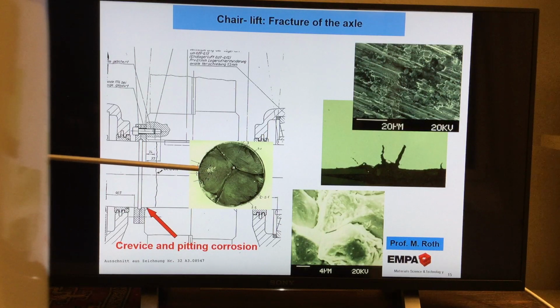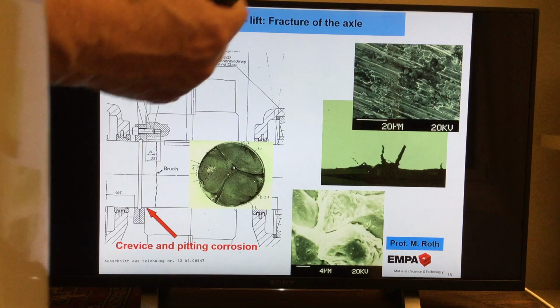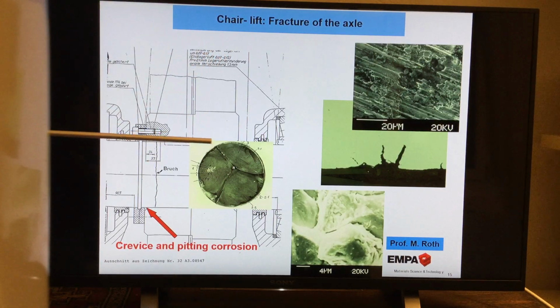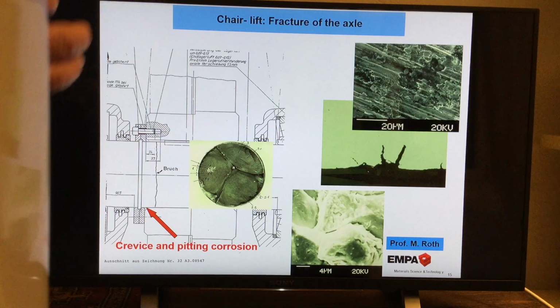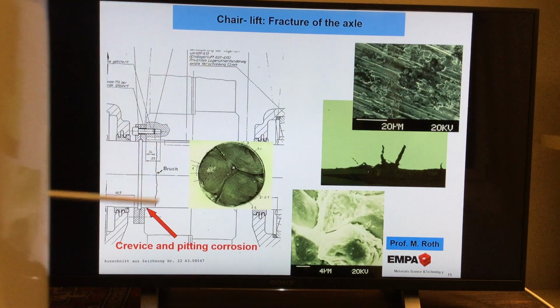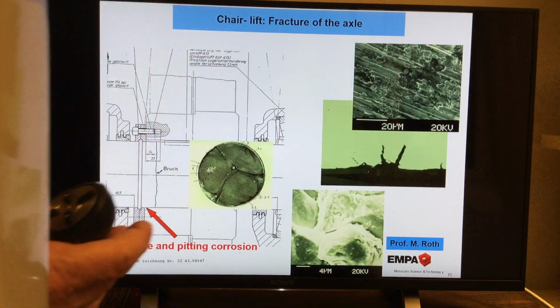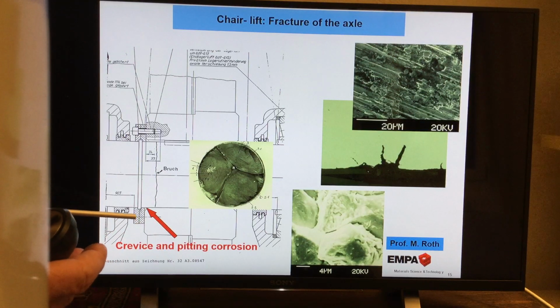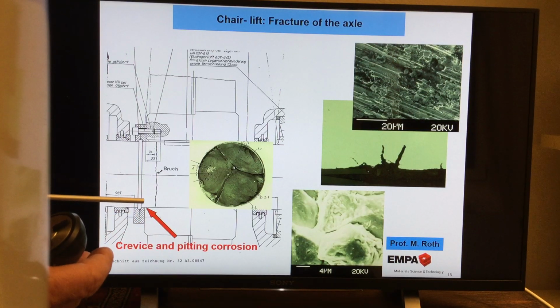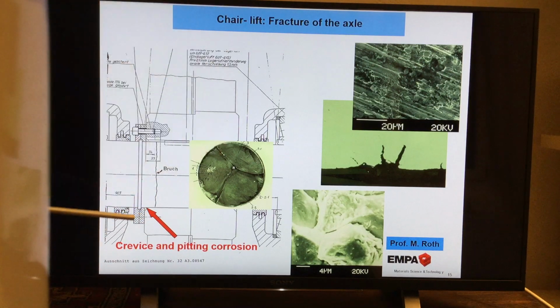The cracks started here between, because you can imagine when the machine is running and here it's fixed and here it is a sort of a breathing. There is a little bit opening of that gap. A few micrometers is enough, and these micrometers suck inside the humid air, and the humidity, the moisture, stays here inside. When the machine is switched off, it cannot dry.